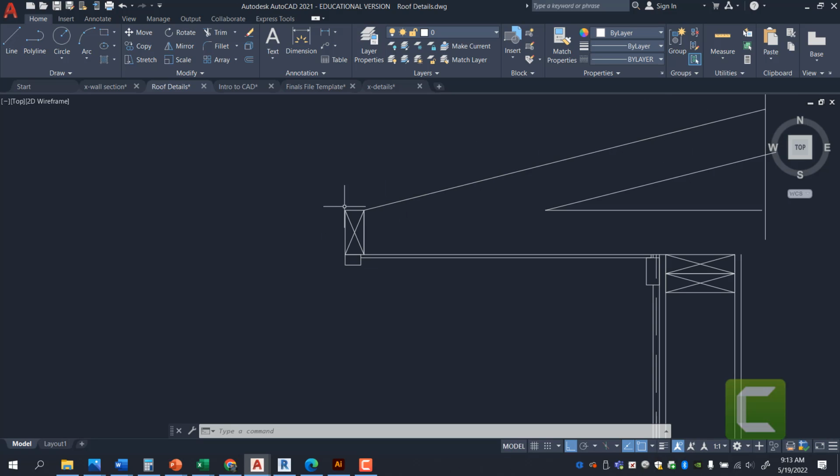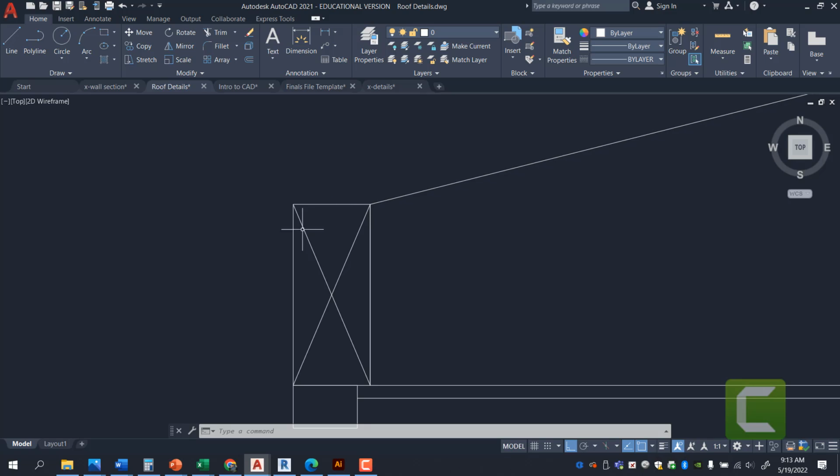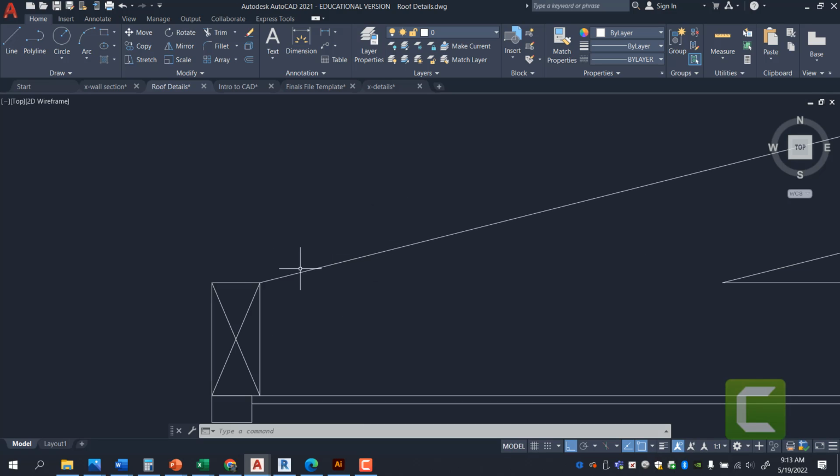So now that you have your roof coming down, you can obviously cut this at an angle and create that slope, or you can have it flush into your truss. What you want to have on top of your truss is your plywood decking. Now, we do 19.5 inches on center in the south. Even if we are doing commercial, we specify minimum of 15/32 CDX plywood.